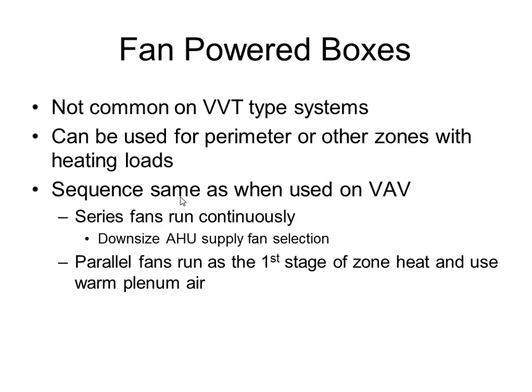You just downsize your air handler supply fan and then use your series fan powered box. Or you can use parallel fans and run the first stage of zone heat as the return air from the plenum. All of Carrier's controllers come standard with an output for enabling a fan. So if you ever have a VVT system with a requirement for fans, that's something that's standard on a Carrier VVT controller.